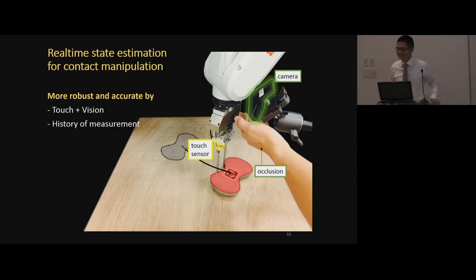Can I ask that? It might be related to Russ's question. So in state estimation, say for vehicles, you would have a zero velocity update, say from wheel and rotor nodes, vehicle stationary, and that can be very powerful in reducing the uncertainty. But if applied incorrectly, it could cause things to go wrong. So what would be worse: applying a contact constraint when you're not in contact, or being in contact and not appropriately estimating that you're in contact?